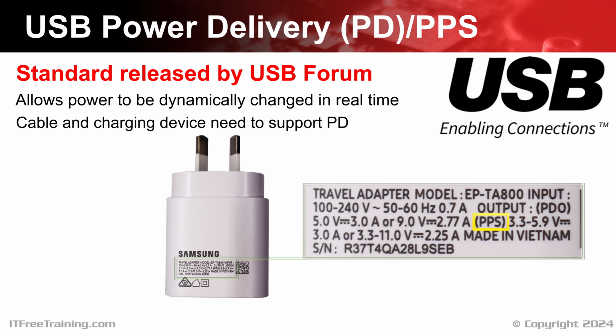To ensure that the charger does not break a device by putting too much voltage down the cable, it starts the voltage low and increases or decreases it as required. If your charger or cable does not support PD, this may mean when your device requests additional power, it won't receive it. Thus, the extra capacity in the charger is not used.